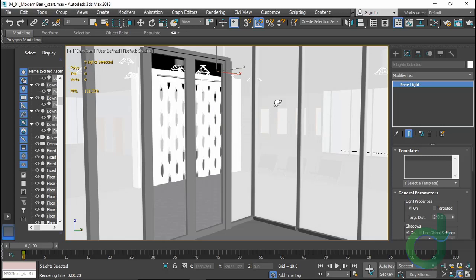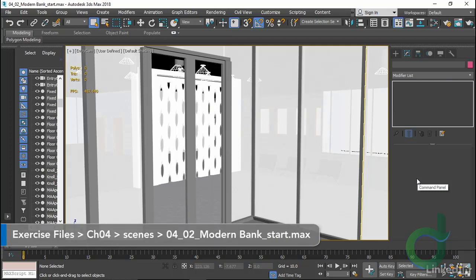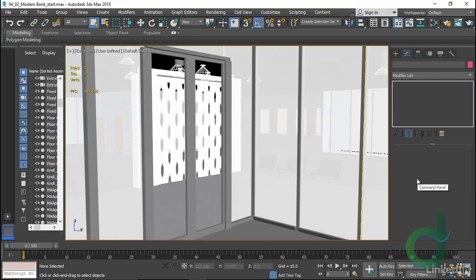In a design visualization, we often want to animate the lights coming on. This can be problematic sometimes to select those lights and turn them on, as the different banks may have different lights in them, different instances. And so rather than go in and select them all, what I'm going to do is add a manipulator on the screen that can control a bank of lights. I'll do this often because I have many lights that aren't always instances or easy to select. Here's how this works. We'll create a manipulator and then wire to it.